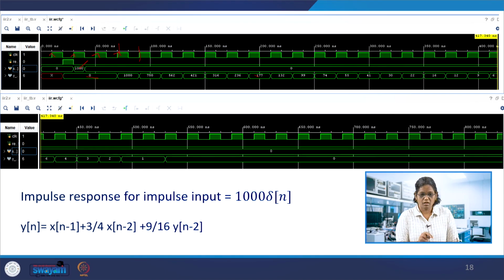After processing in the FPGA, the digital outputs can be given to the D2A, and the analog output can be viewed in the DSO. So this is the complete process of an analog signal getting filtered by a digital filter, and then getting back to the analog domain as in the real world.